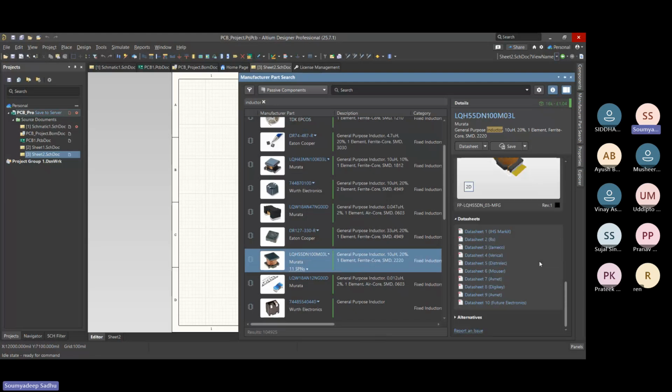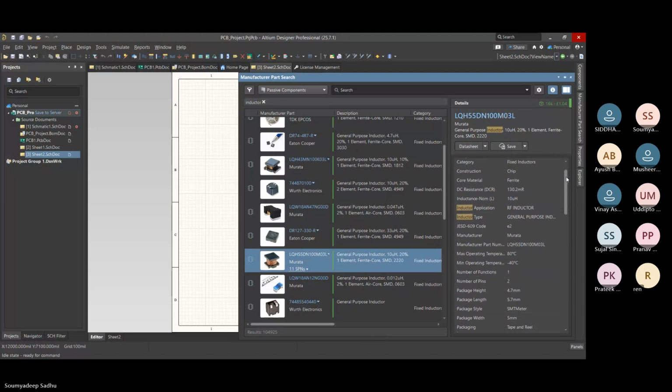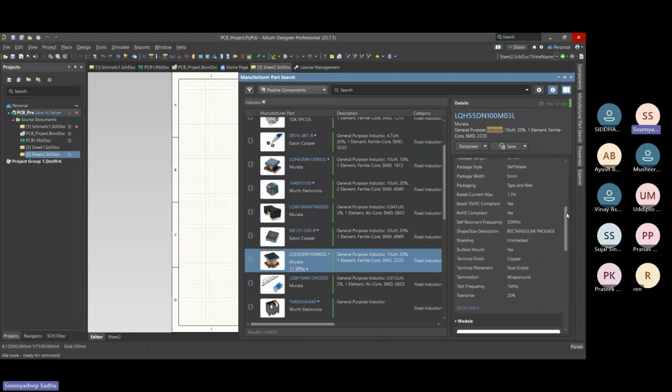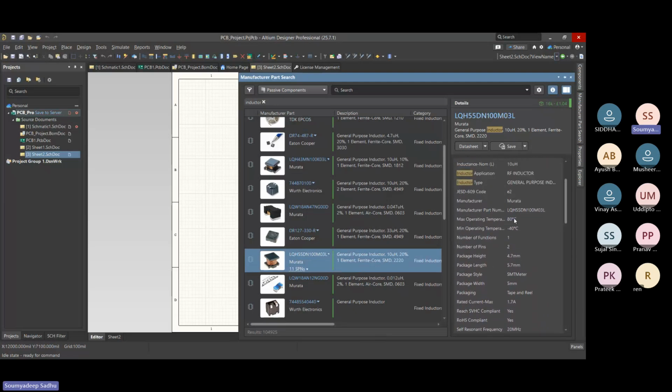So what you have to do is first make your circuit and decide your components. What will be your specification of the circuit? What will be the operating range, the temperature operating range of the circuit? If you are working in this range, well and good, use that. You have to keep in mind that all electric circuits have heating problems.